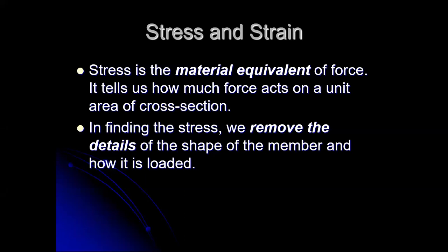What stress lets us do is eliminate all of that and basically come up with one number. If this material is made out of 2024 T6 aluminum, then it can handle 35 KSI before it breaks. I'm making up the numbers, so please don't check me on that. But we'll get to some numbers later.